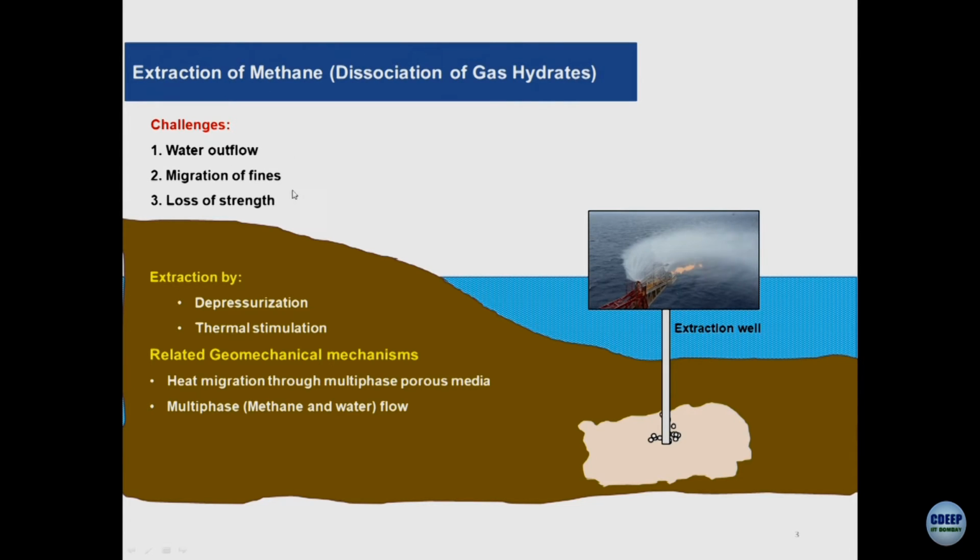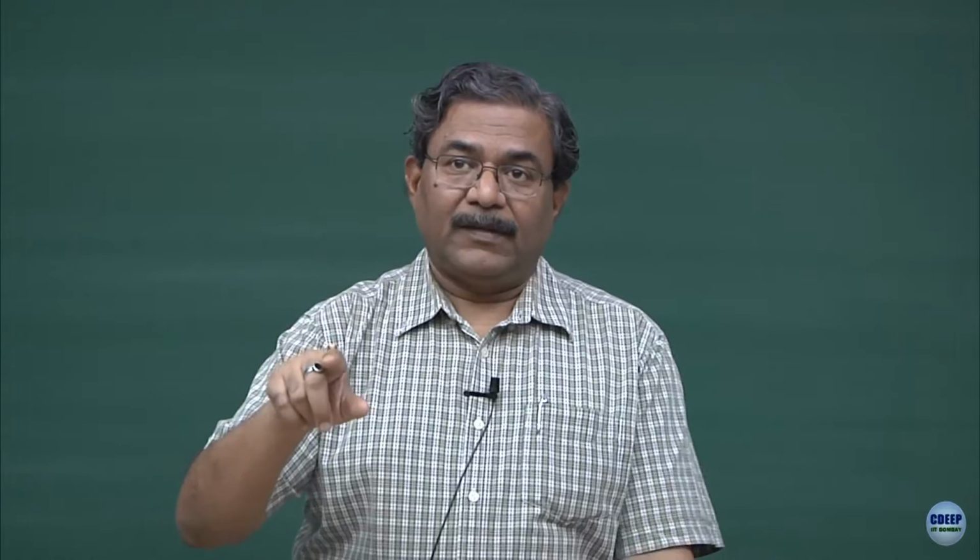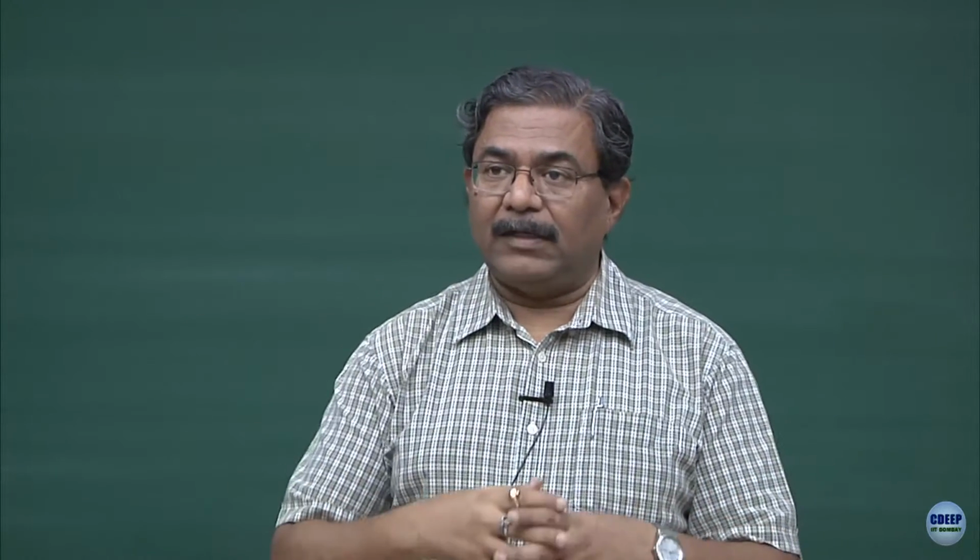So, migration of fines causes loss of strength. All these problems are time and space dependent. Shear strength is a function of x, y, z and t, time. Cohesion is a function of x, y, z and t. Friction angle is a function of x, y, z and t. Hydraulic conductivity itself is a function of x, y, z and t depending upon whether you are talking about the gas phase or the fluid phase, the water phase. So, this problem becomes very complicated, which people are trying to solve right now.